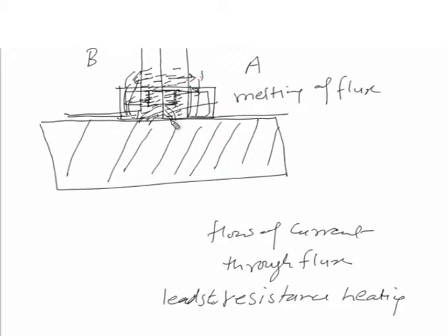The heat being transferred to the base material causes the melting of the edges of the plates to be welded, and once this starts, the solidification of weld metal begins and it starts settling down in the bottom portion. Once it settles in the bottom portion, the open sides of the base material are well covered by the copper shoes, and these copper shoes are in contact with the molten metal and the molten flux.